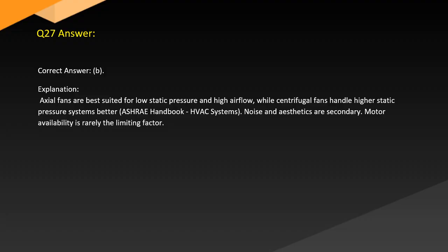Answer. Correct answer, B. Explanation. Axial fans are best suited for low static pressure and high airflow, while centrifugal fans handle higher static pressure systems better. ASHRAE Handbook, HVAC Systems. Noise and aesthetics are secondary. Motor availability is rarely the limiting factor.